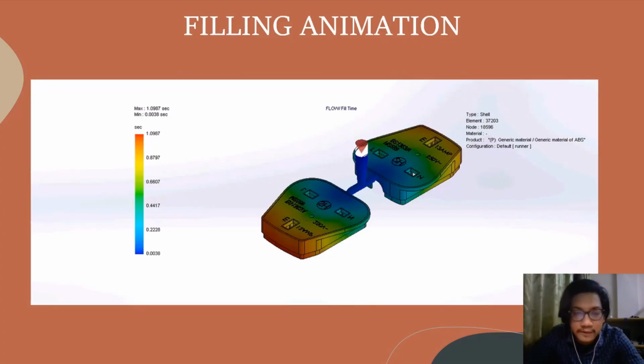Okay, moving to the filling time animation. The filling time is 1.1 seconds. The cooling time is 8.58 seconds. The open mold time is 5 seconds, and the total cycle time is 14.58 seconds. From the diagram, we can see that the mold is filled evenly. Therefore, no runner balancing is needed.